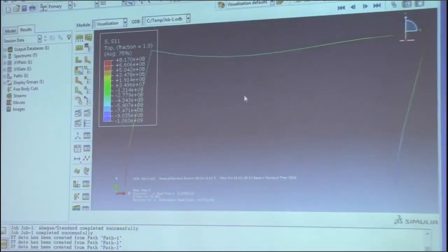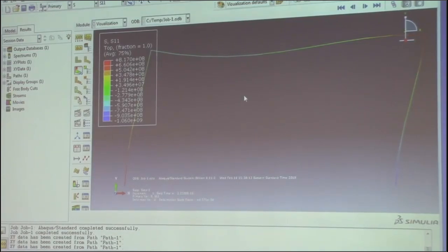And another question is that I already said at the beginning, for different loading conditions, sometimes one element is enough. Sometimes we can only do the approximation because ABAQUS for beam problems can only do the cubic polynomial.